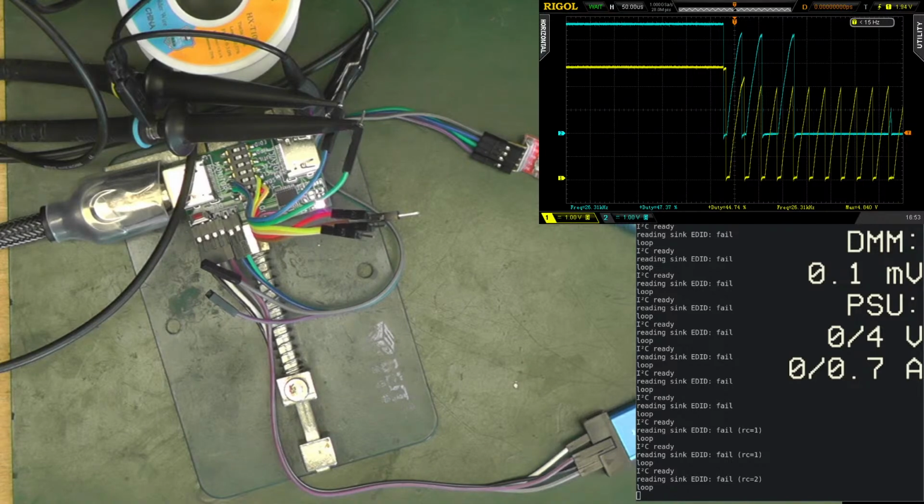So this sets it high, but apparently it doesn't set it high fast enough. I2C delay, get time to get high. I do give a bit of time. So how long is the delay? I2C delay periods. That's one period. So if I make it really slow, it should be fine.